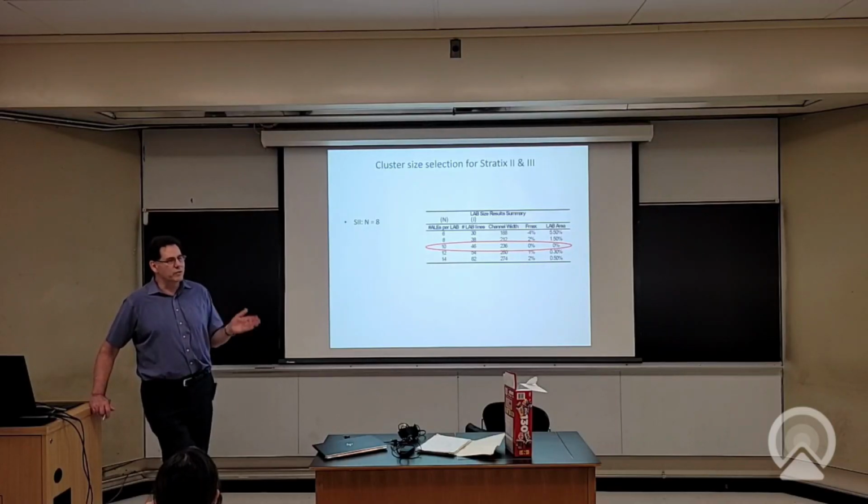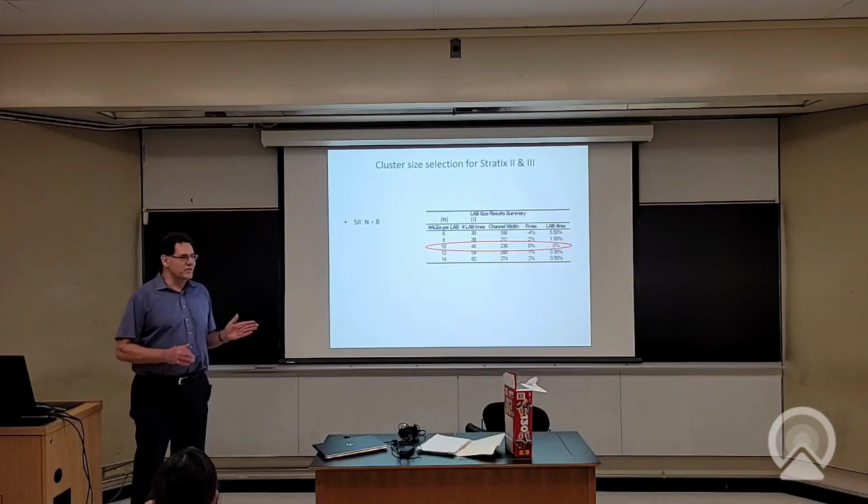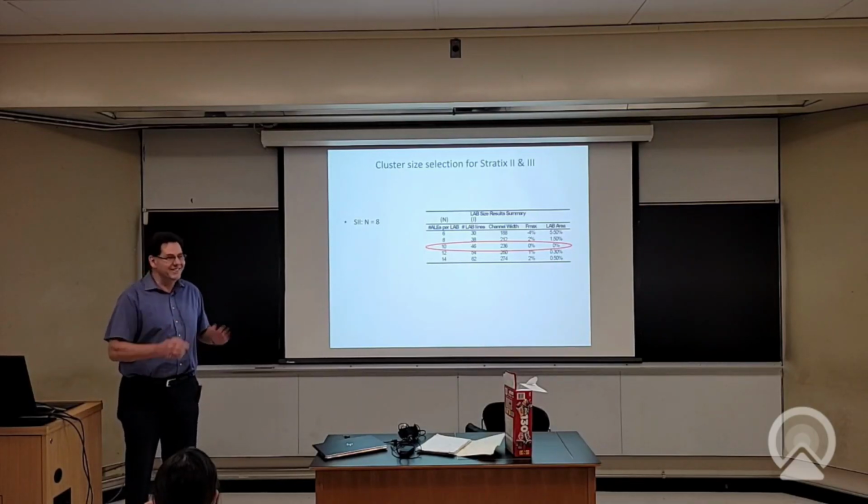So once you add all those routing ports to hook up to the muxes, you start going, wait a sec, okay, so now I've hooked this mux up to everything, and all I can do is a mux, but I still need all these routing ports. So maybe what I should do instead is not make a mux, but make a LUT. Do you know what I mean?